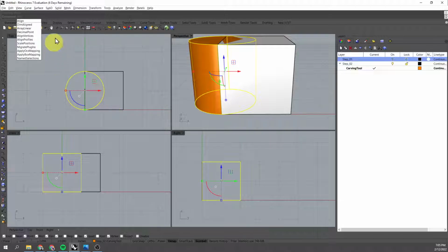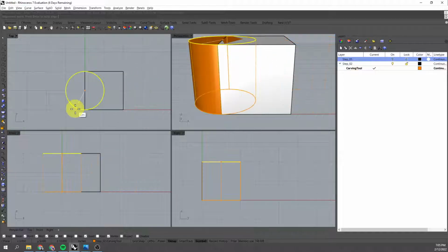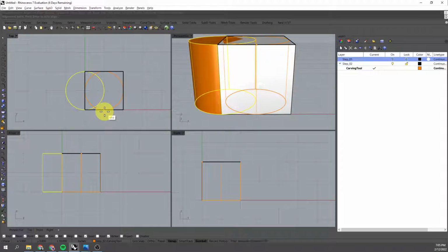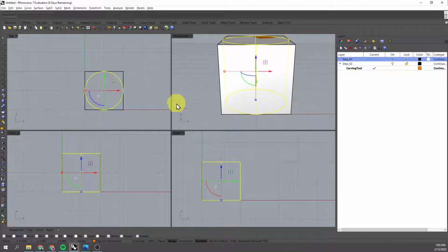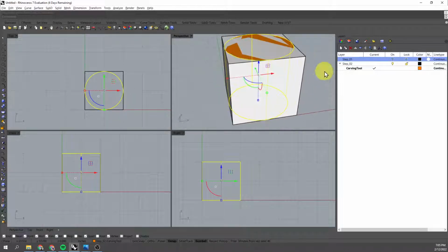Align will be here, and depending on which window you're working with, it'll do a different thing. Let's do align vertically, vertical center. And as you can see, at least from the top view, it'll move my object left and right, and I'm gonna snap it to that middle point. So it's the same result, just different ways of getting to it.